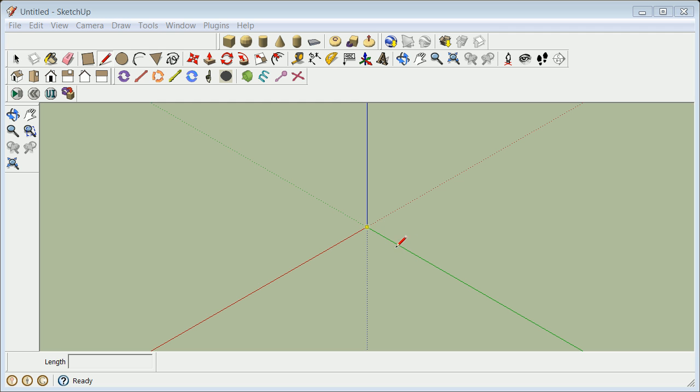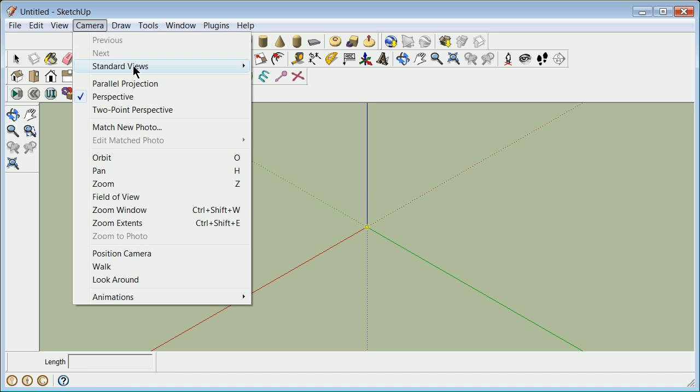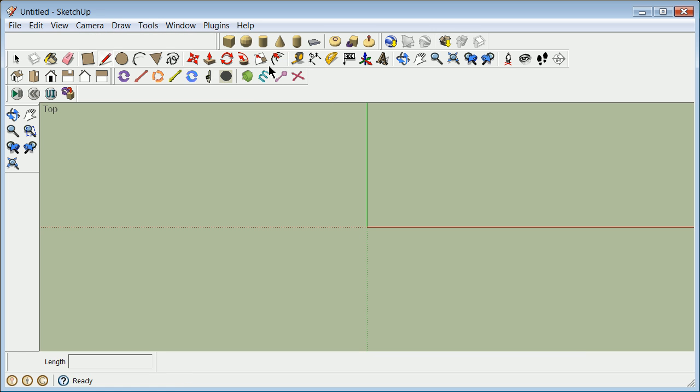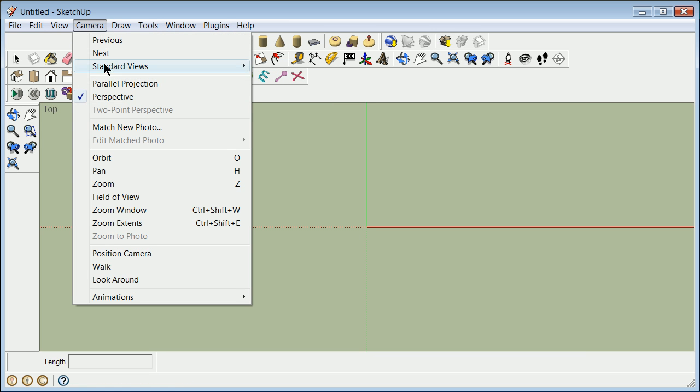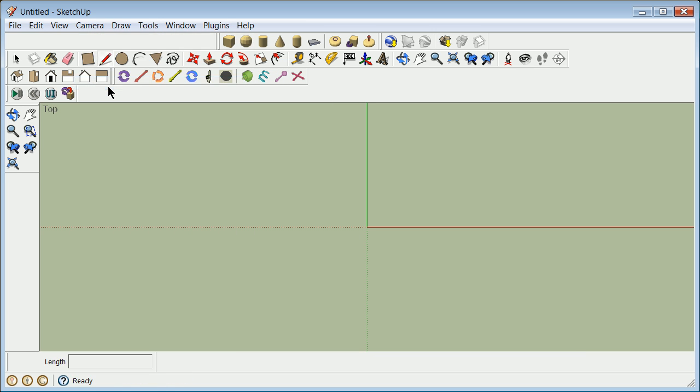You come in typically to SketchUp with a 3D view, because that's by default what it thinks you're going to do. But you can change that to a top view, camera in a parallel perspective, and you've got this general bit here. What I'm going to do is draft 300 feet north and 300 feet east. Instead of using the most basic tools, I'm going to use the relative coordinates, which you're going to see down on the left here.